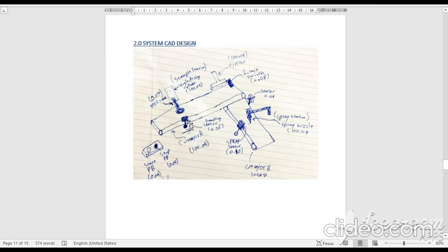Here we also have the stamping sensor, 0.06, and here we have the ejector. Basically the object will move from here and stop once it's detected, then continue after the process finishes, with the timer, as we will see later in the program. The ejector will be activated when the limit switch has been touched. So the ejector will move like this, and the object will move